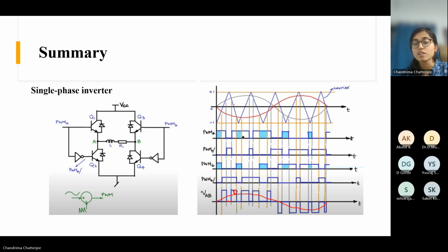So the filter value basically will reduce. If you want the same attenuation for bipolar and unipolar, for bipolar you will have to use bigger filters.